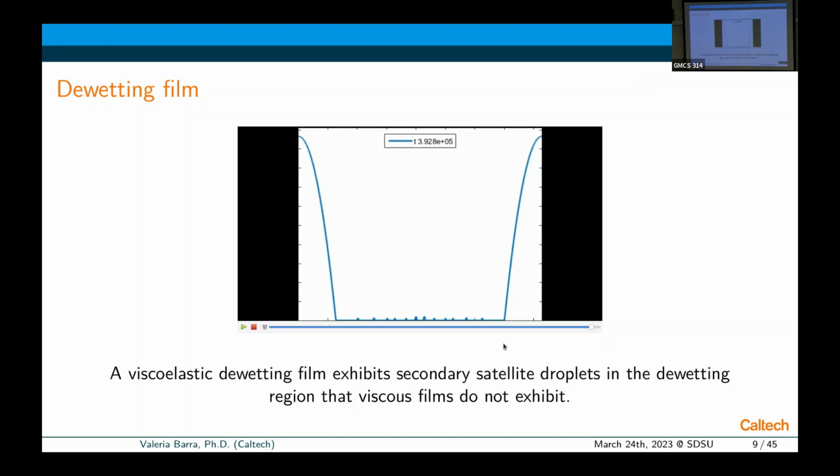And how does the resolution of your mesh affect the algorithm? We did several studies with several different resolutions, and they're all persistent. So they were not dependent on it. Of course, we were able to fully resolve this with the grid size chosen, so we saw that they're not affected by the grid size. If you increase the grid size, of course, you're not resolving.